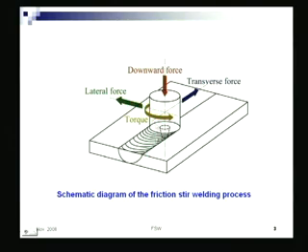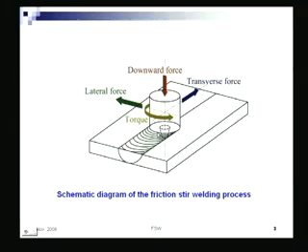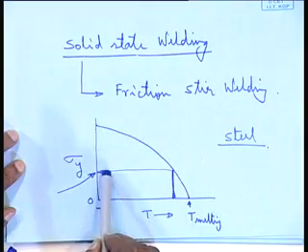That pin will have a sufficient blunt diameter. It's not like a drill bit, which cuts in and goes inside. So here you need a much higher downward force to have it plunge through. But obviously, once the friction starts, the stress required becomes less.